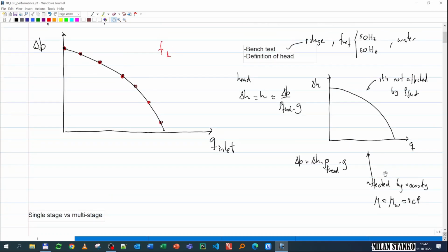Many oils that we produce in oil and gas wells and fields have high viscosity, but this is at standard conditions. When you go to a high temperature, typically the viscosity can be quite low. So 1 centipoise, 1.3, maybe 3 centipoise. And because of that, in many cases, I could still use the curve of water.